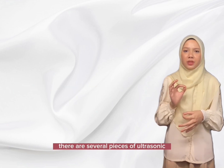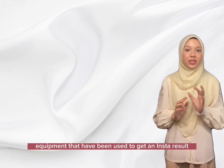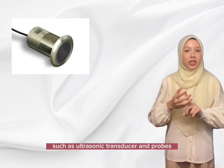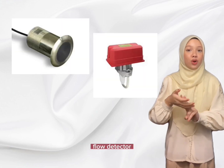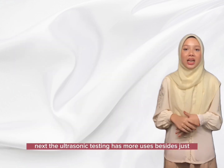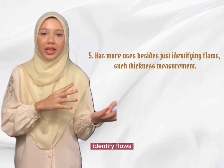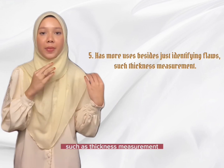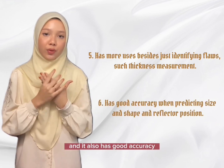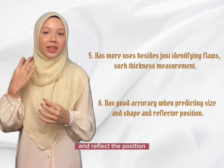There are several pieces of ultrasonic equipment that have been used to get an instant result, such as ultrasonic transducer and probe, flaw detector, thickness gauge, and automated UT system. Next, ultrasonic testing has more uses besides just identifying flaws, such as thickness measurement, and it also has good accuracy when predicting size, shape and reflector position.